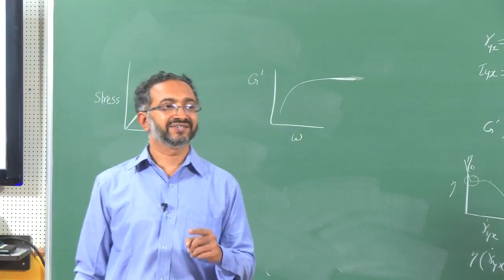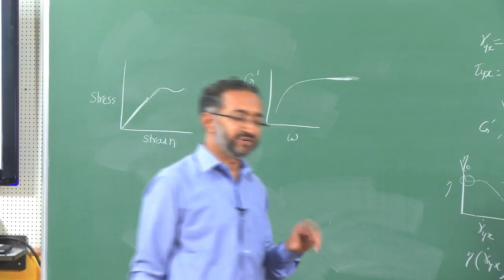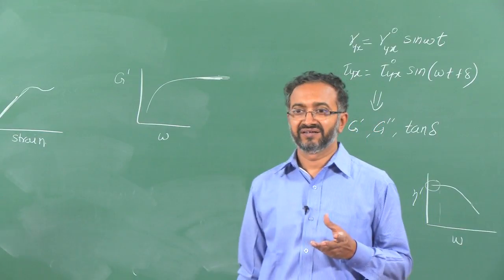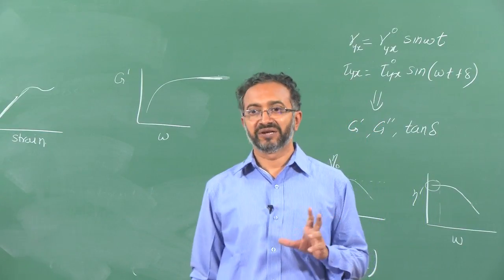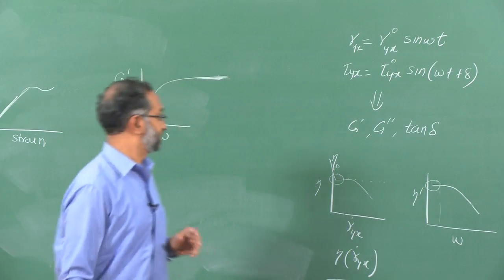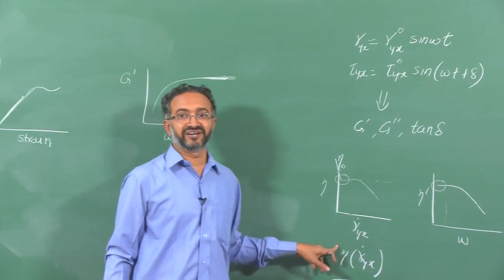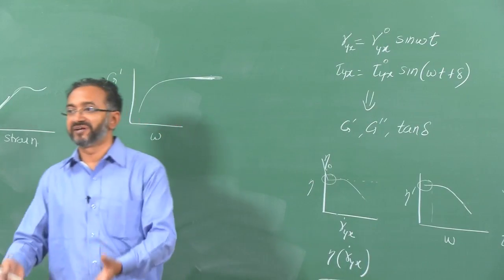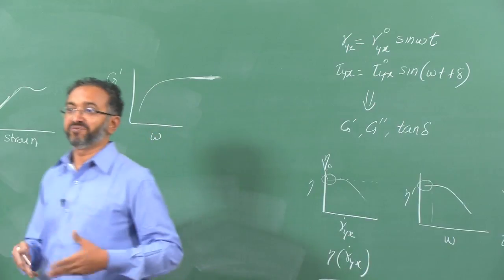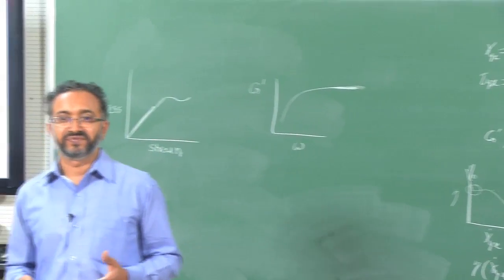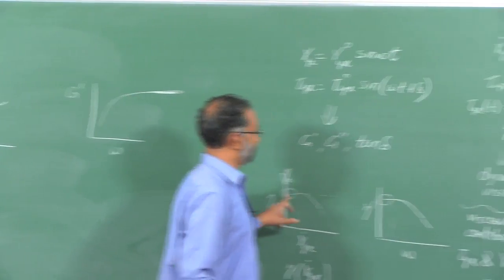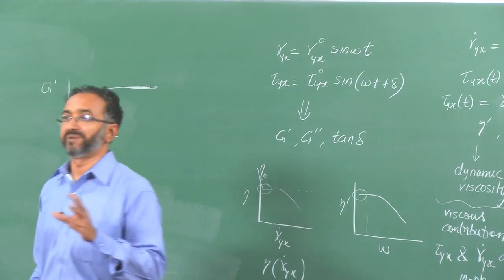So, in both cases the material is being examined beyond the largest relaxation time of the material. So, those ought to be similar. No deformation actually. Huh? In both cases we will not. Yes. So, even though you are doing steady shear you will confine yourself to low deformation. Therefore, both in the end become an identical type of material response. So, the eta 0 that you measure from here and the eta 0 that you measure from here ought to be the same.